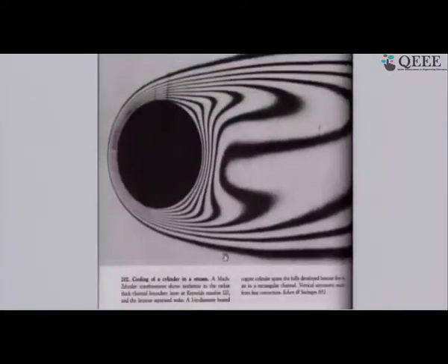And there are very few pictures that we will see. This is the case of a cylinder at a Reynolds number of 120, which has been heated, on which air is coming in at a lower temperature, and we have used what we have learnt in physics, what is called a Mach-Zehnder interferometer, to see the density gradients.